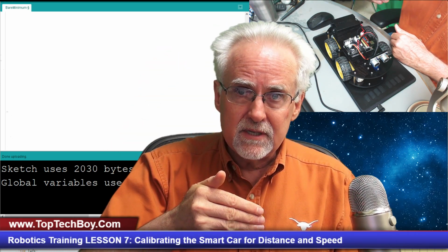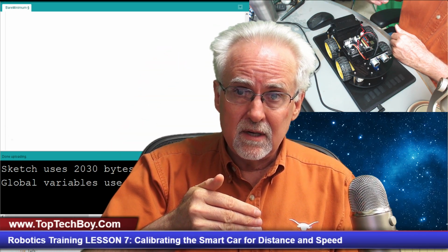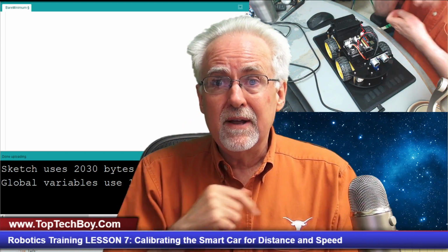Before we were changing the speed, we could set the distance that we wanted it to go, and it would go that distance. But when we changed the speed, those functions broke. So your homework this week was to go in and fix your code so you could drive the correct distance independent of what speed value you wrote to those enable pins.